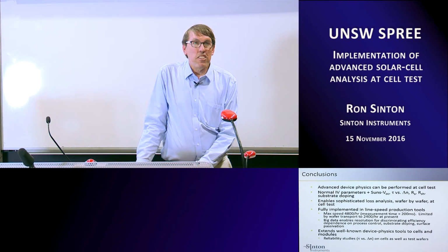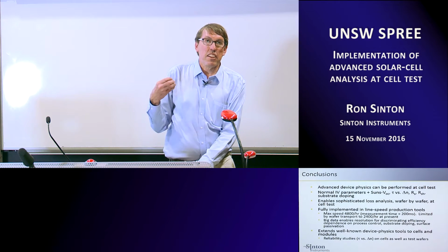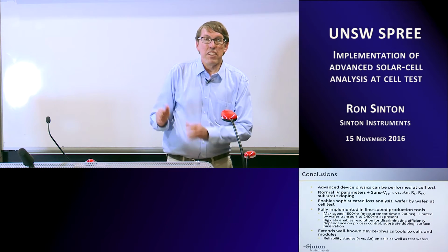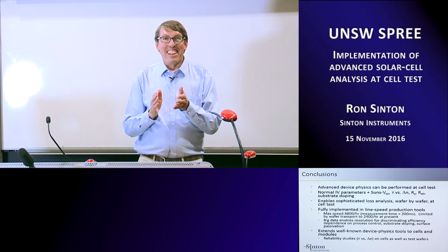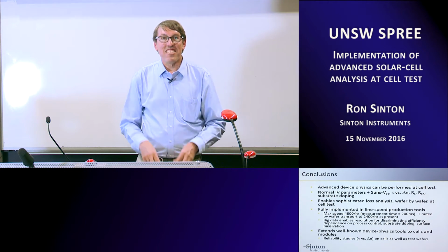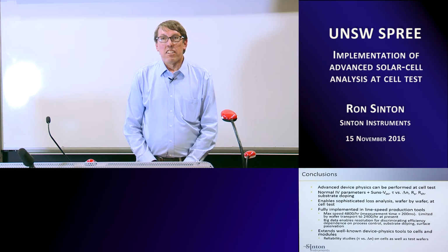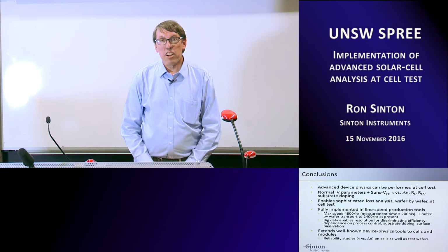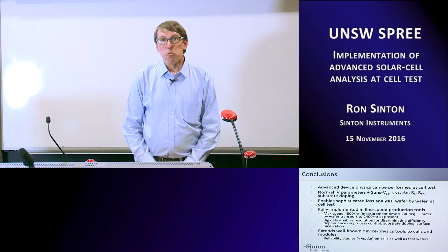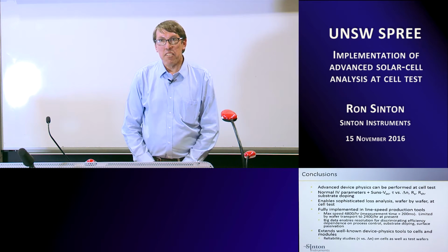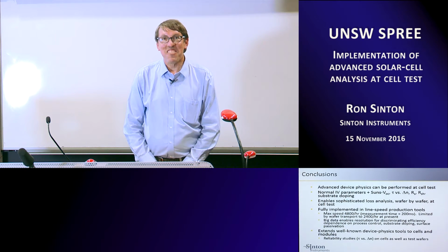It's very difficult to know phase shifts with a high degree of precision because you have time response of the intensity detectors, and you have phase delays in the hardware as well as the device under test. So we use a combination of things to try and minimize these errors. So you do want to take advantage of every shortcut you can get away with, but you can't get away with all of them.